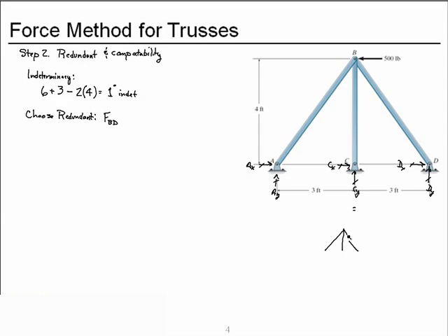We'll cut it, and it has the applied load, and this will open up an amount delta BD, and we'll superimpose the axial force in BD times a situation where we have a unit force acting on the ends of this cut, and it will cause an overlap.